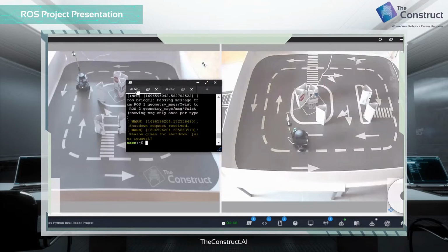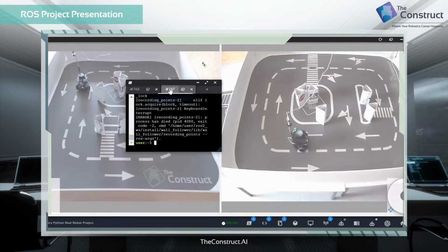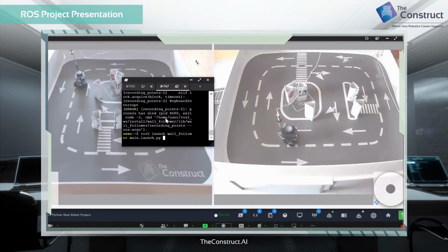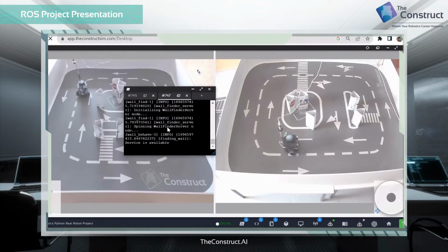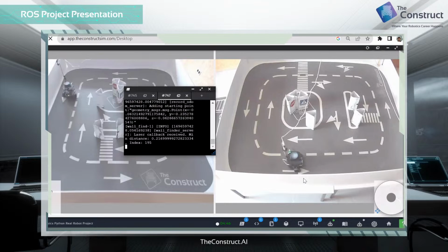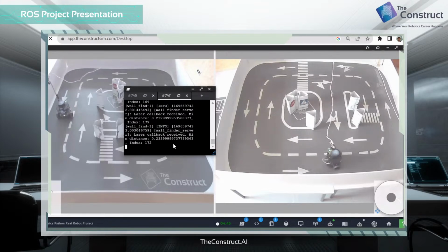Yeah, okay. So let me run the ROS bridge and connect it. Now I'll run my code and let's go. As you see now, the robot is finding the nearest wall. When it reaches it, it finds it. Now it should keep 0.3 meter distance. When it aligns the right side of the robot, it will start the wall following behavior, and it will start also the readings, the ROS action readings.